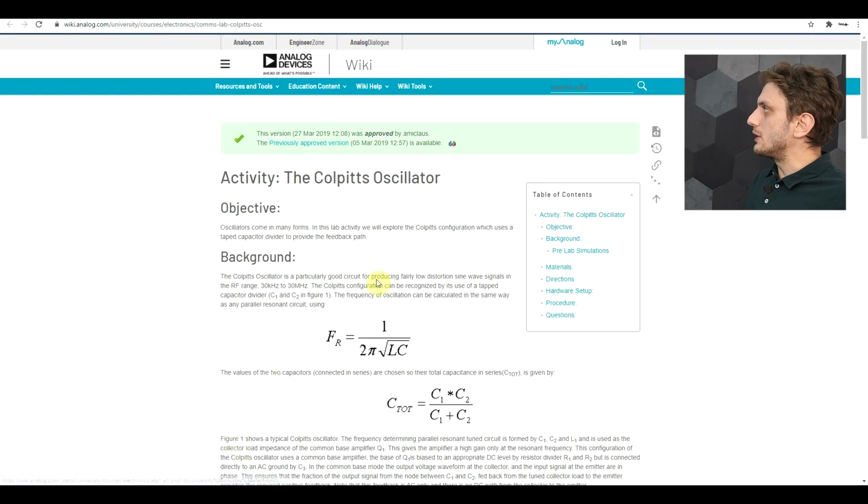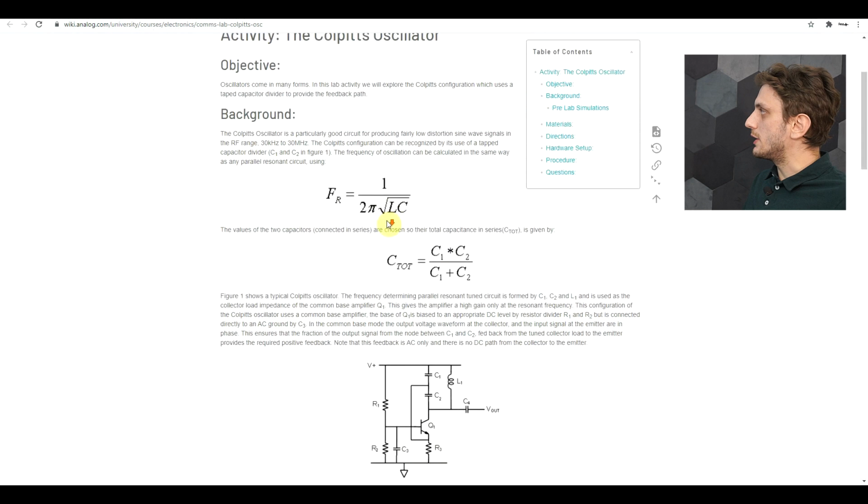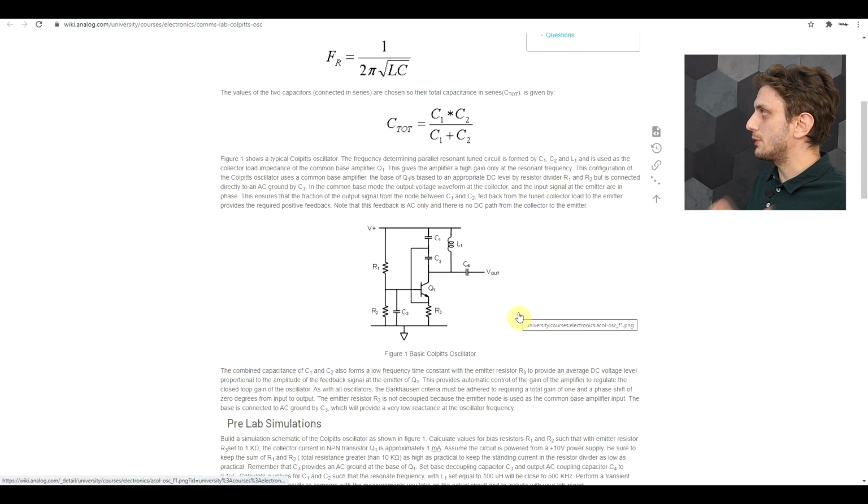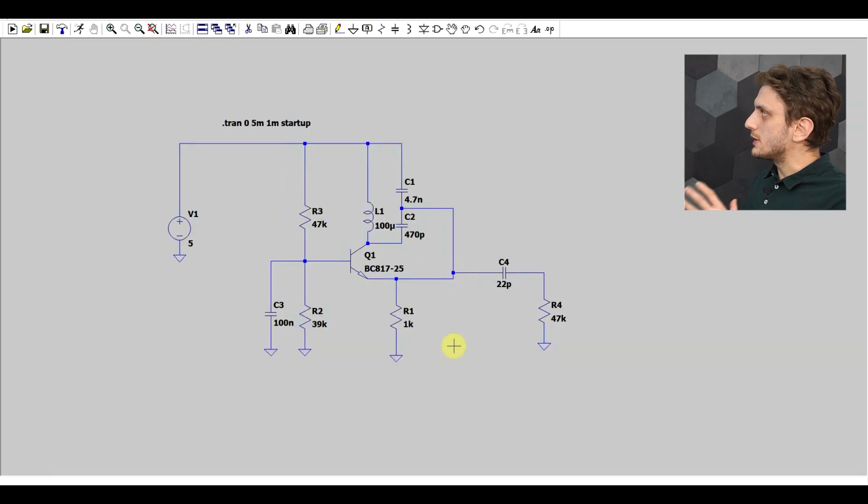Now, for the oscillator part, I will be using a basic Colpitts type of oscillator, so this is its basic schematic, and the nice thing about this oscillator is that it's pretty bulletproof, so every time I build one of these things it always worked. And these will be the exact components I use. So my supply will be 5 volts. I want to supply my circuit from the USB adapter. Since I want to take the signal from the computer, might as well take the power from there.